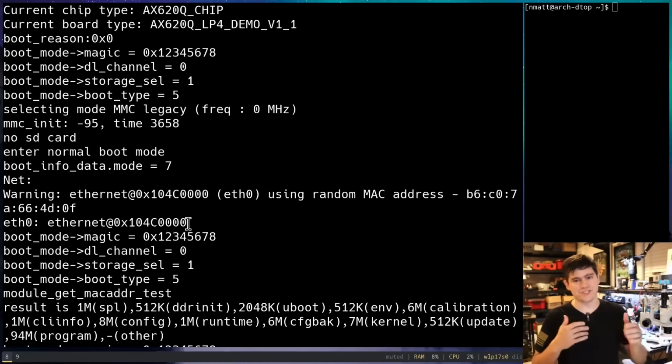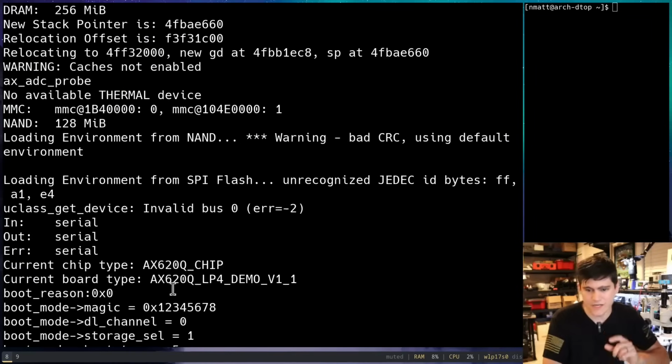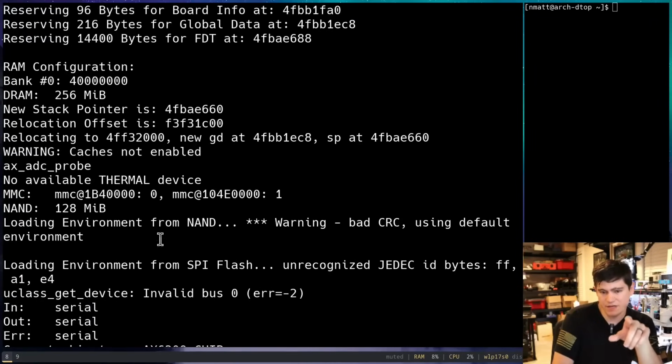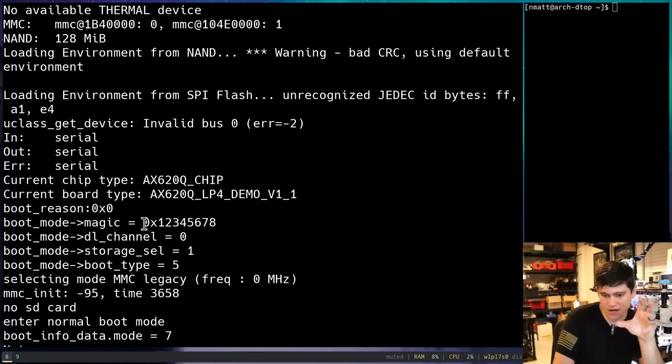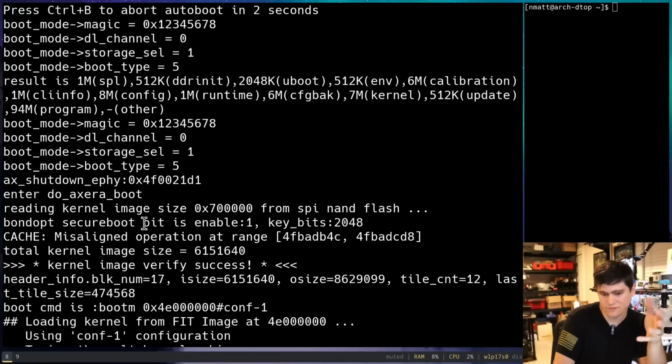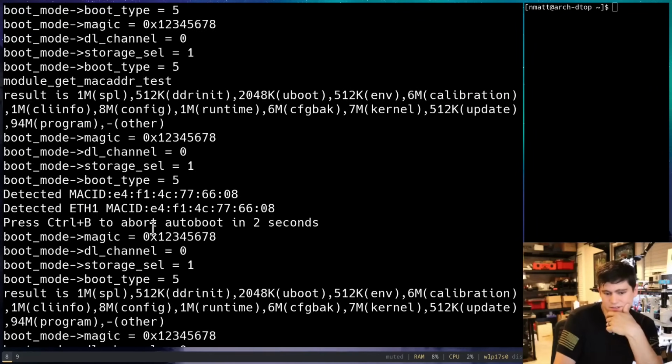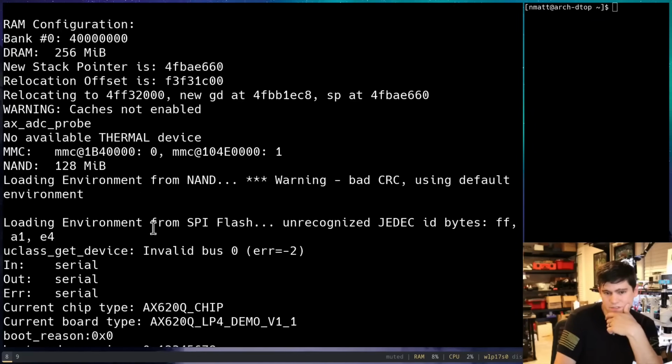Sometimes it's just a 50-50 shot to figure out which one is the VCC pin and which one is the receive pin on the board. Sometimes the receive is floating around, but sometimes it'll just show up as 3.3 volts on a target board. But we're going to look at this output and see something that gets printed that catches our eye. Or at least it did. Now I'm not seeing it anymore. All right, where's our prompt?